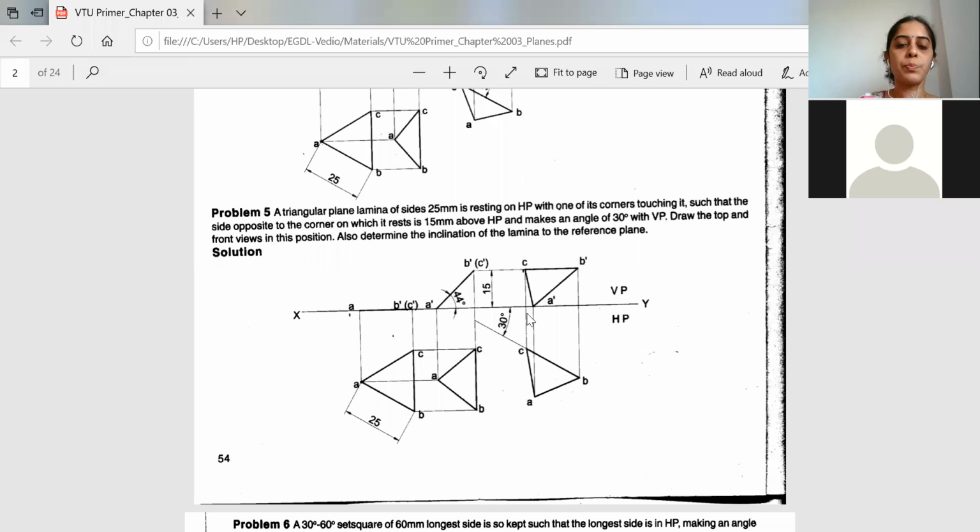You will take the projection from each locus of the top view above. You have to show the directions. Here the direction is not shown, but see that you show it, and then you extend the projection from here as well. Locus of C, locus of A, locus of B, locus of B dash and C dash come along the same line.